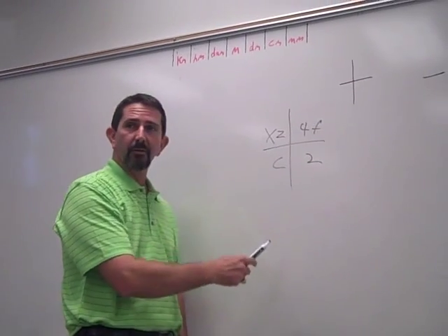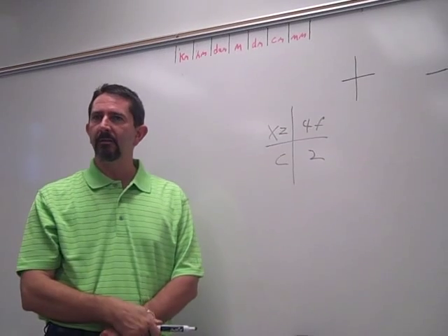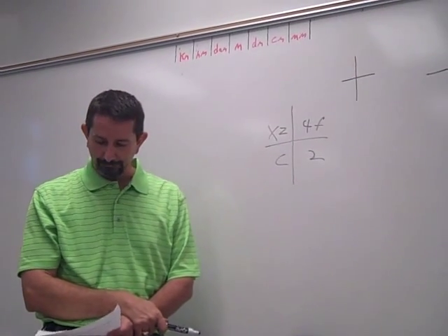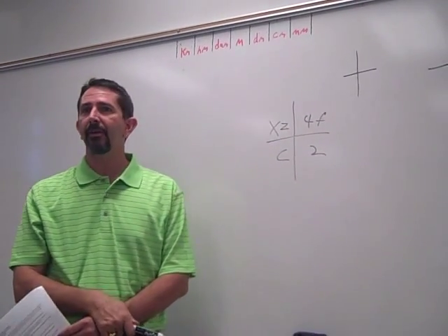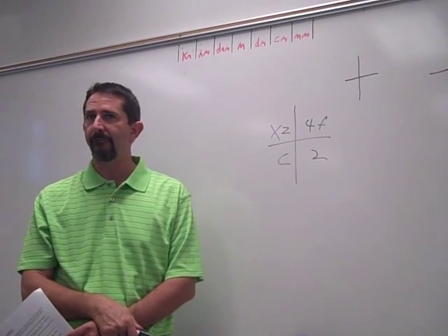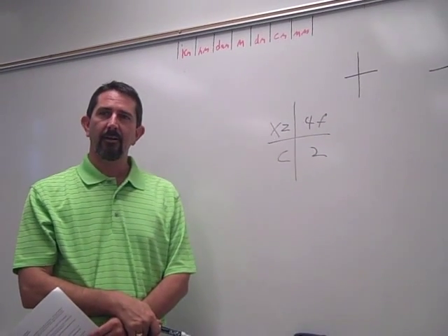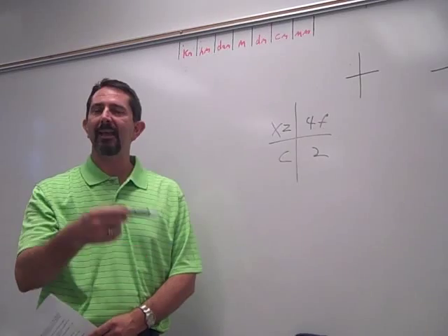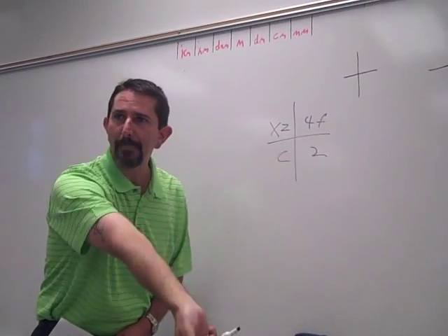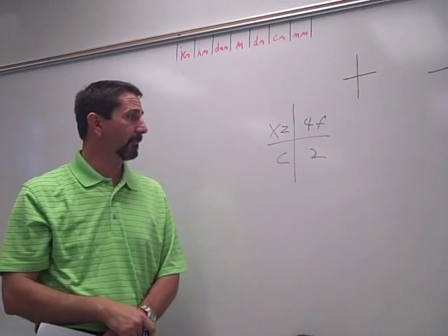The second thing I can learn by looking in the second quadrant is 4F. 4 is the diameter of the hole in 32nds. So the hole that I need to drill for this fastener is 4/32nds. F tells me that it's a far side, that the head of the fastener goes on the back of the part, not the front. It's very important for assembly.